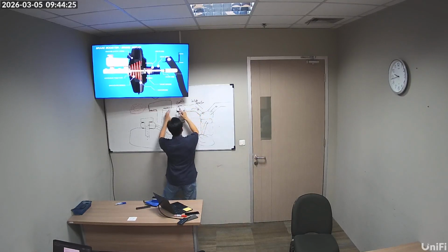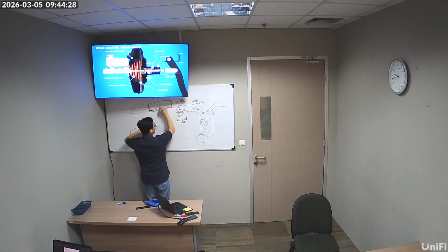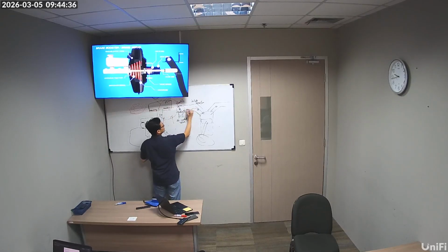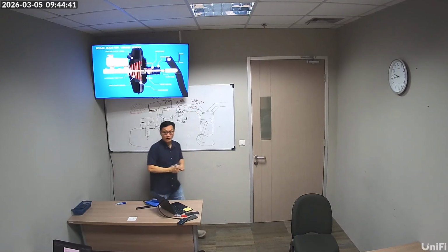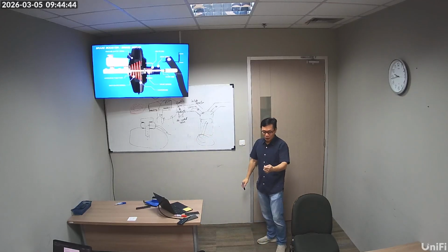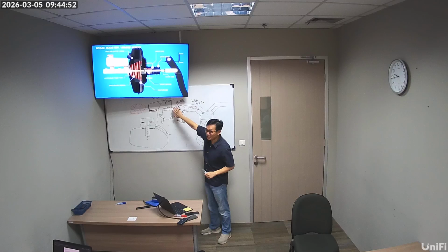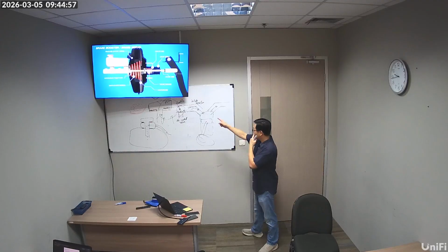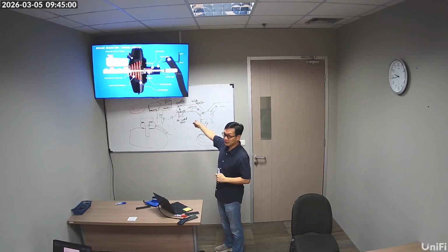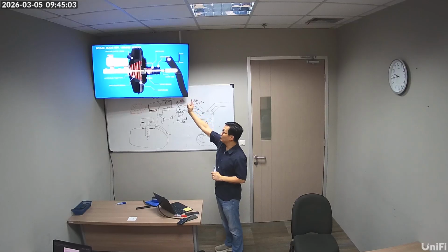And so this is surrounding air outside. This is your air filter, and it's wide open. But here it's choked, and so here there is vacuum. Quite a strong vacuum, I should say. If you try to hold your hand over the throttle while the engine is running, you can be injured. It's a pretty powerful vacuum. So again, this is the vacuum we're going to tap to help us with the brake booster.